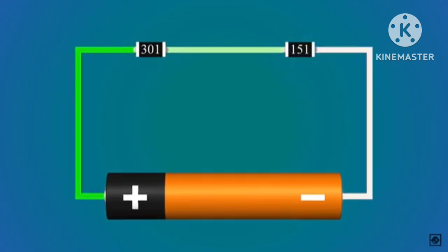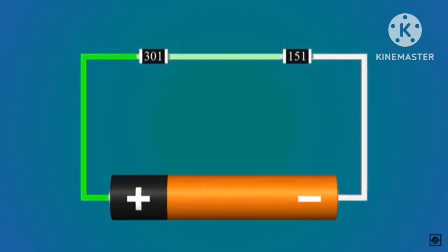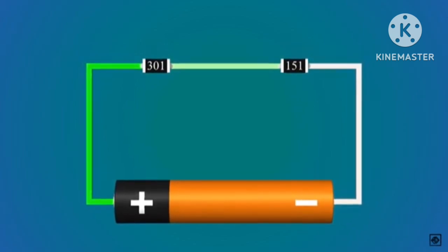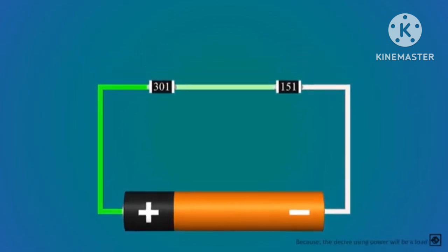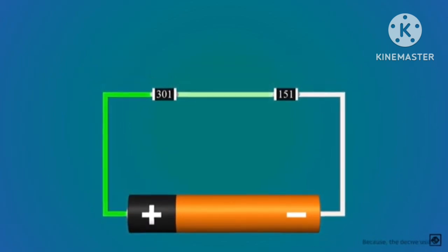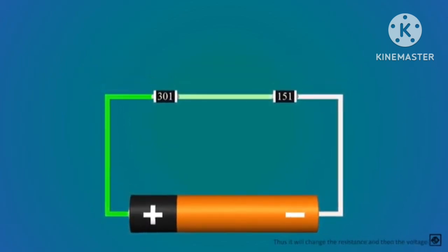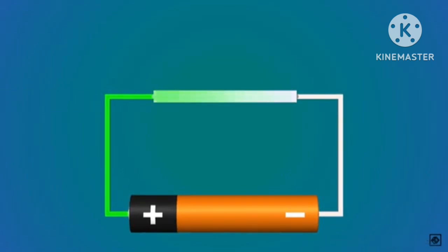And now what you have is a voltage divider. Voltage dividers are to be used only for references. Using them to lower voltage and act as a power supply will cause issues. You can obtain any voltage with the voltage divider, provided it's between the two terminal voltages. Now, if we add more resistors, then we can have multiple points for referencing the voltage.